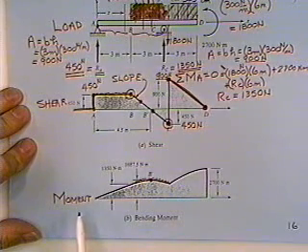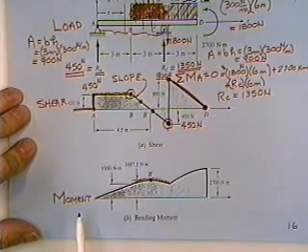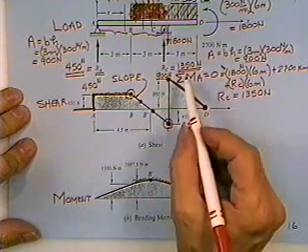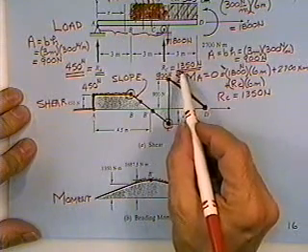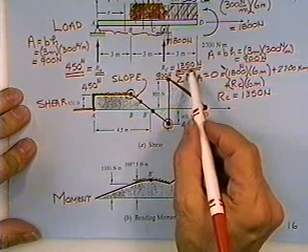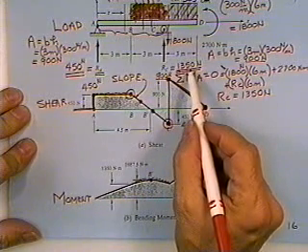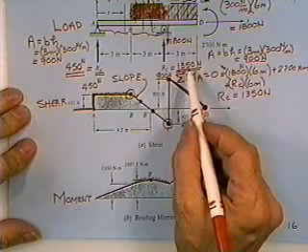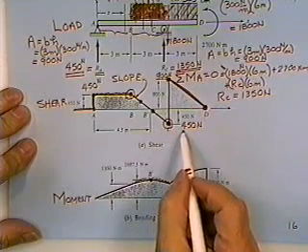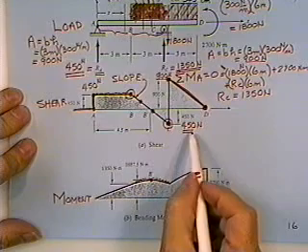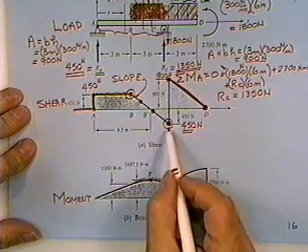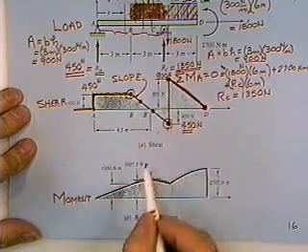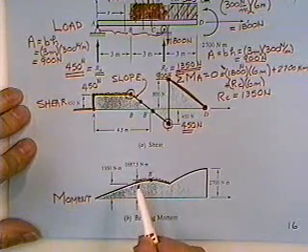I can assure you that one of the answers on the quiz will assume that you think 1350 is the worst shear, because that's the biggest force I see acting on the beam, 1350. It just so happens that the 1350 does not get into the beam. At first, it's 450 required just to overcome how far the shear diagram was below the line, and then it kicks the diagram up to 900, so the peak shear for use in the equation is 900 newtons.